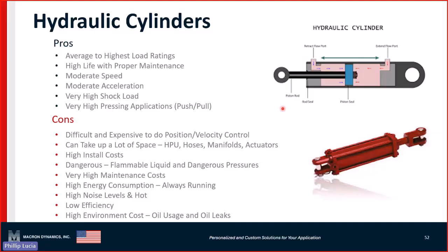Going the next level up, a hydraulic cylinder. A hydraulic cylinder is pretty much the same thing as an air cylinder, except you're using hydraulic fluid as a media. It's the same principle. You put fluid into one side of a piston and it pushes the rod back and forth and vice versa. They do have the highest load ratings, just because of the way a hydraulic cylinder works, with just filling it with oil. It has a lot of force per area.